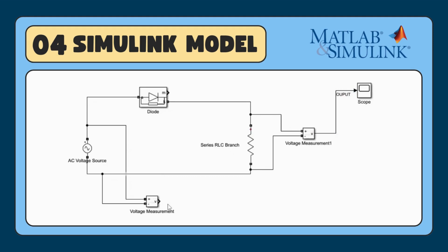The purpose of the circuit is to convert an AC input voltage into a pulsating DC output using a diode and a resistive load. For block 1, which is the AC voltage source, this block generates the input AC signal. It produces a sinusoidal waveform with a fixed amplitude and frequency, typically 50 or 60 Hz. This waveform alternates between positive and negative values, representing an AC supply.